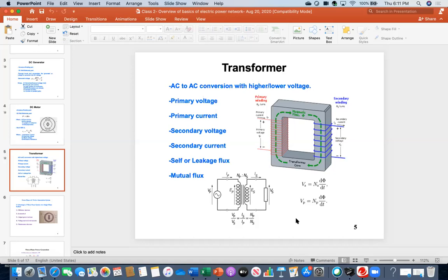That is the basic property of an inductor. Like, for example, what is the basic property of a capacitor? Across a capacitor, voltage can't change instantaneously. And across an inductor, current cannot change instantaneously. Therefore, because current can't change instantaneously, I am answering your question whether it can be used as a filter or not.